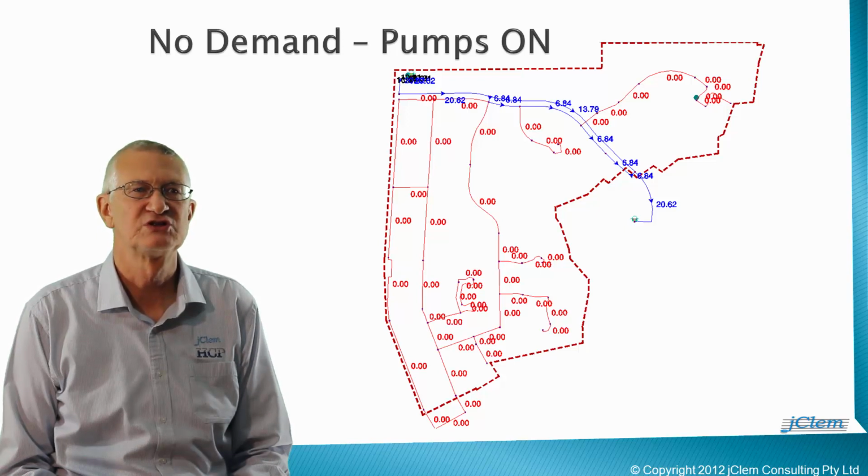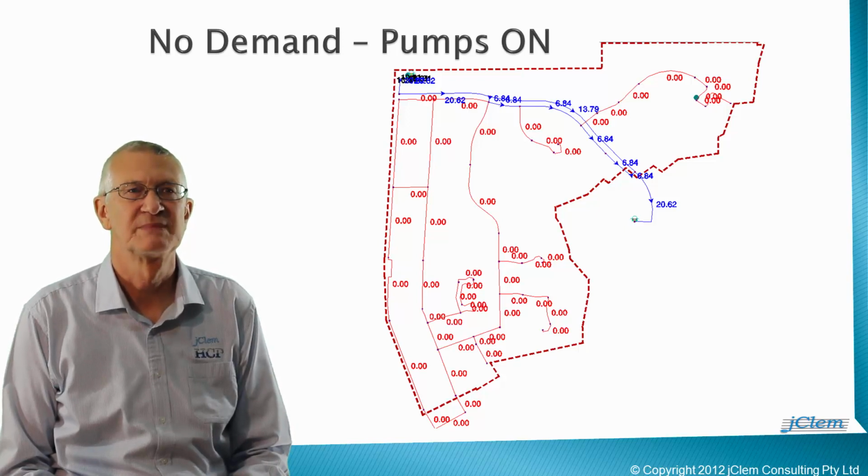However, pressure surges propagate throughout the whole system. The scenario will generate surge amplitudes different to other scenarios. Only by transient analysis can you understand if this scenario creates the worst outcomes, and if this is true in some locations and not in others.